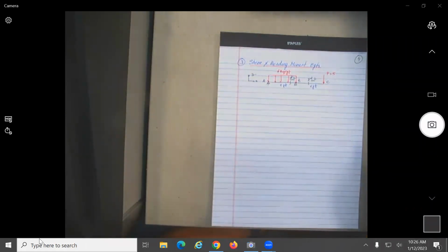Any question about this? How to find the cuts should not be new. You should have done that in statics and solid mechanics, no? All right. So we have the 2 cuts. So now, why do we make the cuts? So that those internal forces called shear and bending moment become external. And we can apply summation of forces and summation of moments.